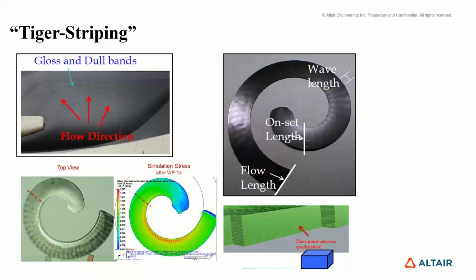And then it hesitates, and because they slow down, the eddy current dissipates, and then gravity can take over and starts dropping it down again until it develops more eddy current, and then stops the drop, and then it pauses, and rinse and repeat. So when it starts to do a cycle like that, it creates this dithering effect. It drops and stops, drops and stops.